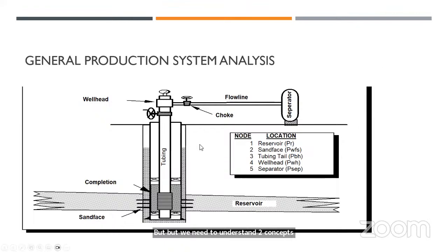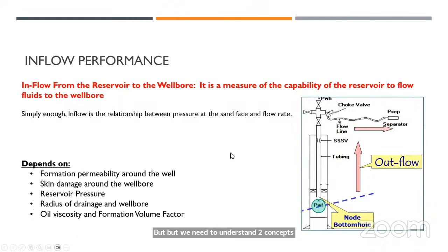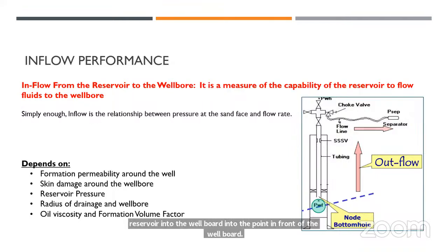Okay, we already were introduced to the inflow performance. Inflow performance means the relationship that controls the pressure losses that happen from the reservoir into the wellbore, into the point in front of the wellbore. It is a measure of the capability of the reservoir to flow fluids to the wellbore.